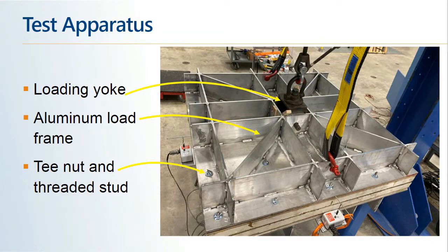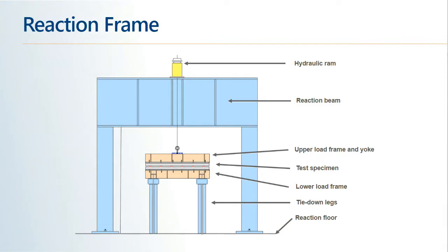This photo here was a picture that was taken on a test run, and we found that the galvanized washers couldn't stand up for the load that was being put onto the sample. So you'll see in other pictures that we actually switched those out for something a little more substantial. So the samples were then attached to this reaction frame, and the reaction frame at the top had the hydraulic ram, and that's how the pressure was, or the load was put onto the samples in the frame.